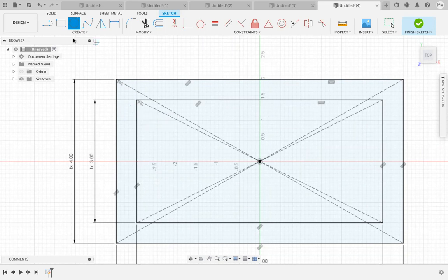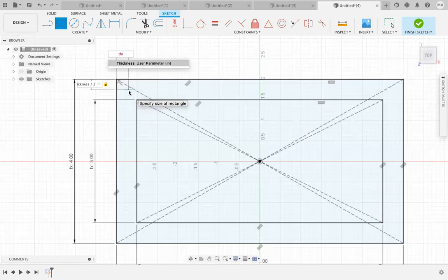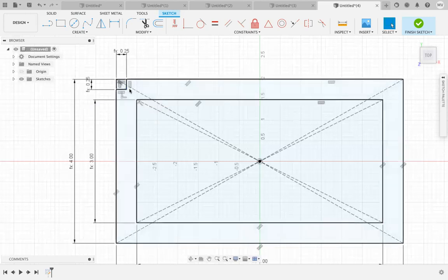So I'm going to show you 2 different ways to do it. The first way is what I did before. I could make a rectangle, and it's going to actually end up being a square, and I want it to be thickness divided by 2 and thickness divided by 2. And now the corner of that is exactly in the middle of both the top edge and the left edge. And if I place my circle right at the corner of this rectangle, it's centered. That was our goal.